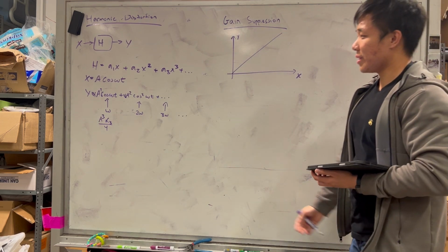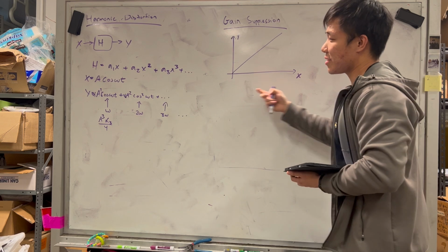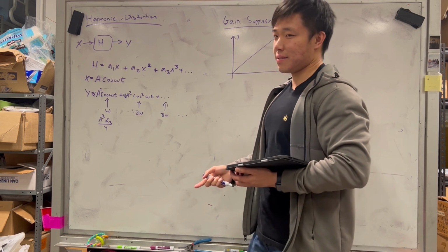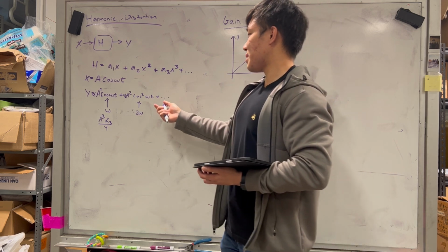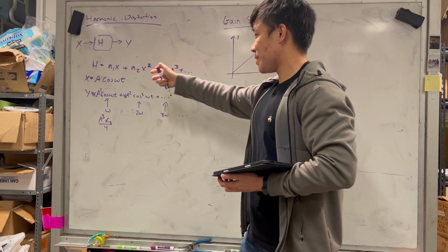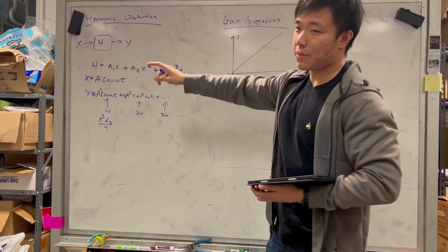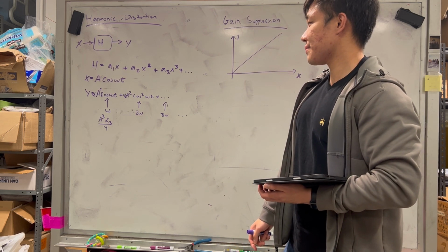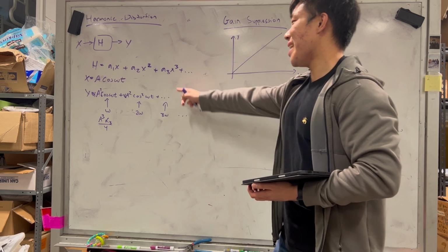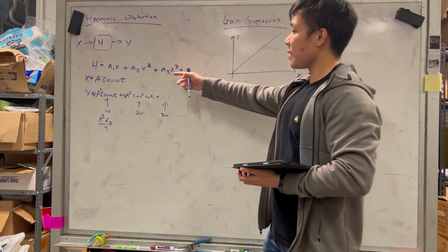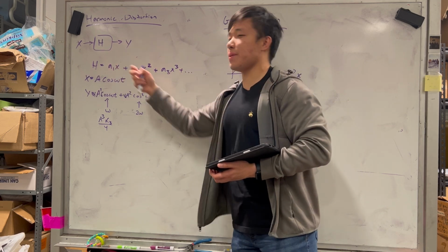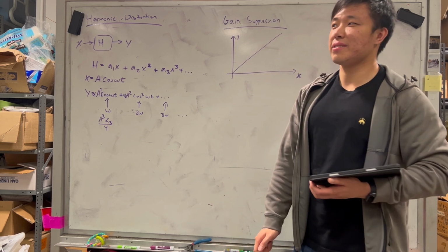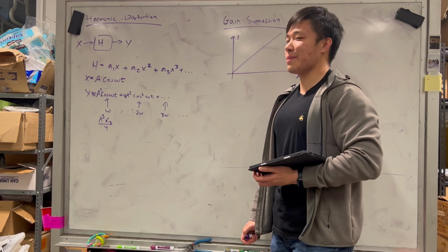Now, with this, as X becomes larger and larger, these terms become more and more significant. And it turns out most systems are compressive. It doesn't matter really what sign alpha 2 is here, but alpha 3 and alpha 1 typically have opposite signs. In most systems, these two have opposite signs because most real systems, if not all, are compressive. I can't really think of an example of an expansive system or a system that blows up.